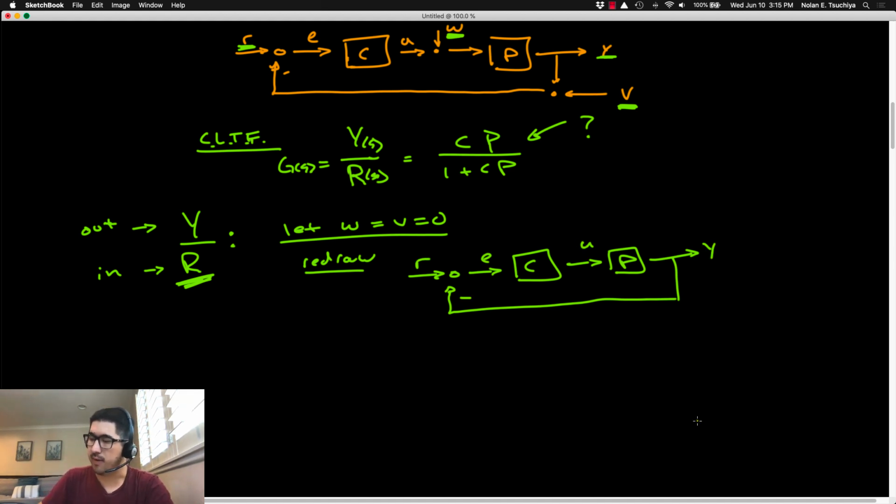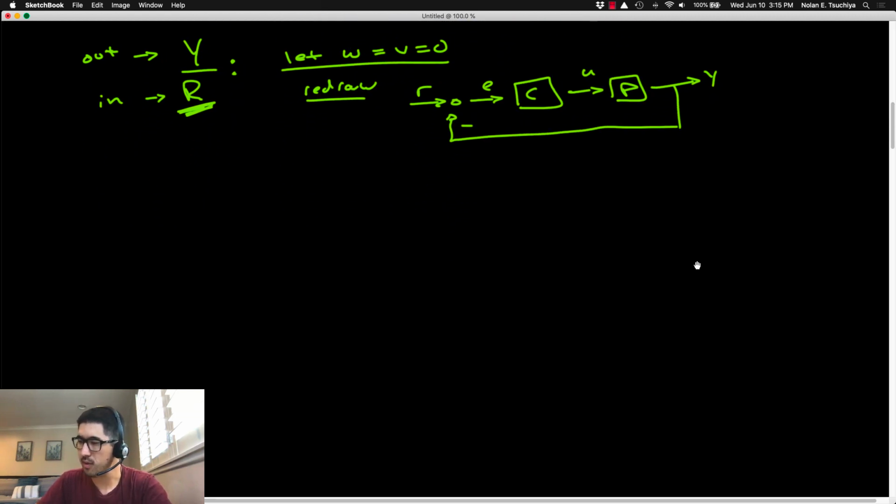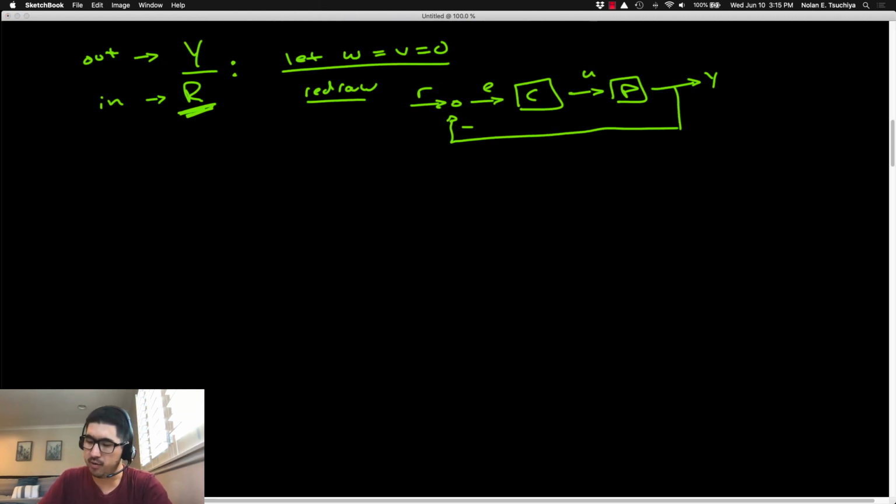And this will simplify things a little bit. Okay, so there's no more V, no more W. And now this is our reduced block diagram. And then the next step that you're going to do is to take a lap all the way around the block diagram. Don't miss anything. Just go all the way around and basically try and extract equations from the block diagram.